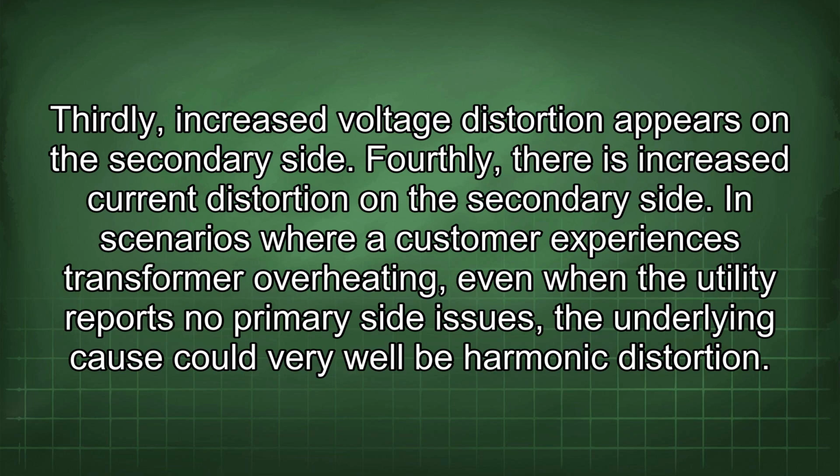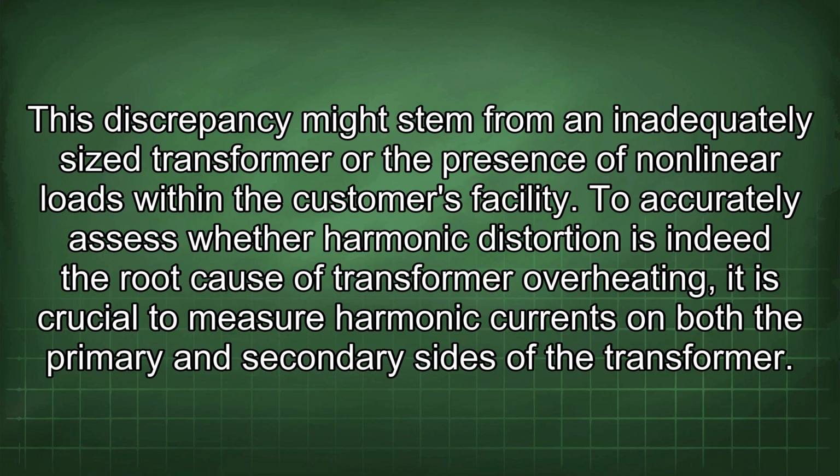In scenarios where a customer experiences transformer overheating, even when the utility reports no primary side issues, the underlying cause could very well be harmonic distortion. This discrepancy might stem from an inadequately sized transformer or the presence of nonlinear loads within the customer's facility.